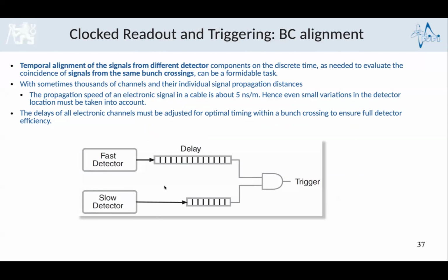Okay, there is a very important thing that one will experience in real life, not only in big experiments but also in small ones, even for prototyping tests in beam tests. One has to take care of the timing of the signals that we are sending to our readout equipment, the data acquisition equipment. We have to work with the temporal alignment of the signals from the different detectors, from the smallest experiment to the largest.